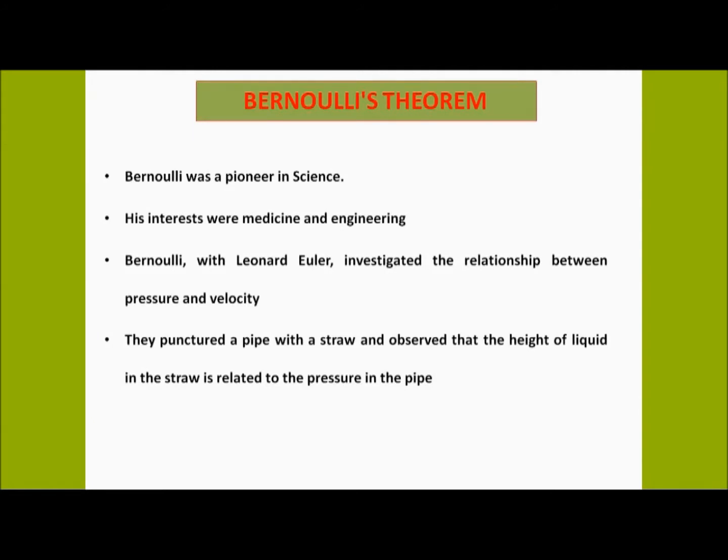If we make a hole in that pipe and put one straw in it perpendicularly, the height of the fluid which comes out from the straw is related to the velocity, or you can say the pressure, of the fluid which is there in the pipe.